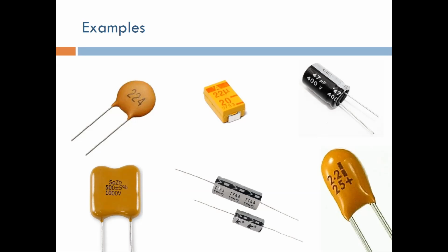Because the rating is usually on the average of the production run. So sometimes some capacitors are weaker than others. So it's better to be safer than being right at the edge of the specification where something can go wrong. So be sure when you're using a capacitor that you know the polarity first. Even if you're using a very low voltage, if you use the opposite polarity, it's going to explode. If you have 5 volts and you put the capacitor on the opposite polarity, it's going to explode, believe me.